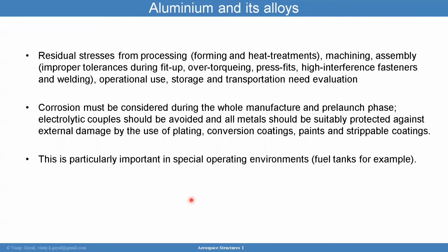Corrosion has to be considered through the whole manufacturing, also including the pre-launch phase, and electrolytic couples should be avoided, and all metals should be suitably protected against external damage by using plating, conversion coatings, paints, and strippable coatings. So very important to keep in mind.